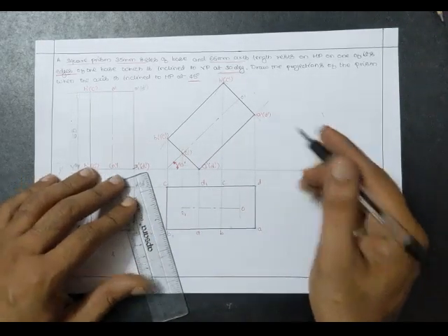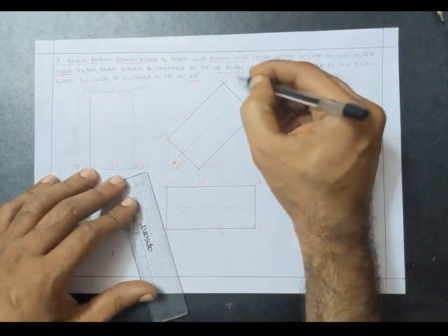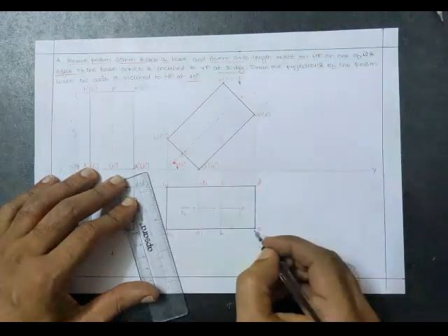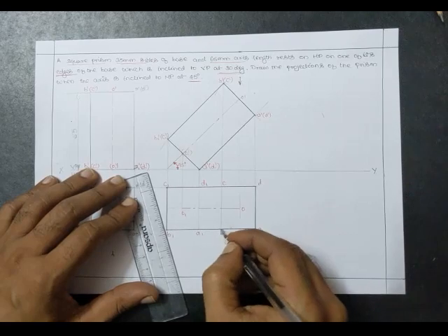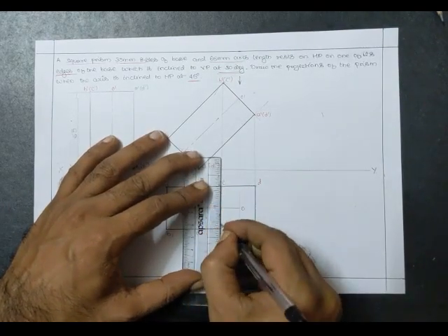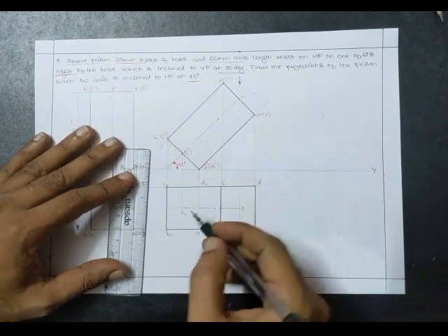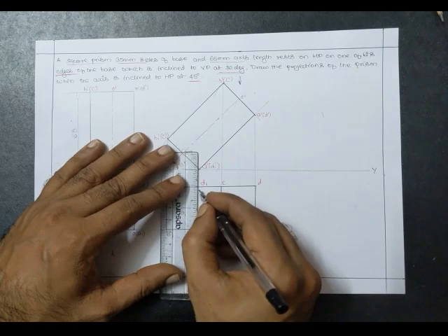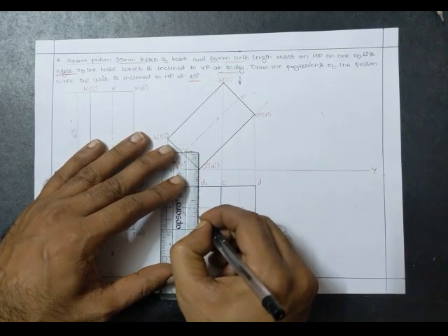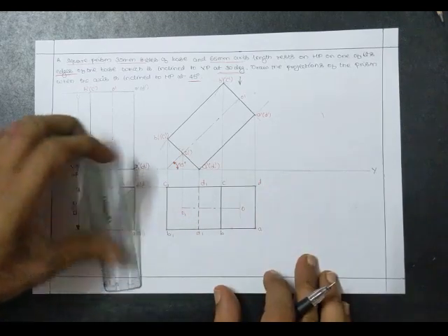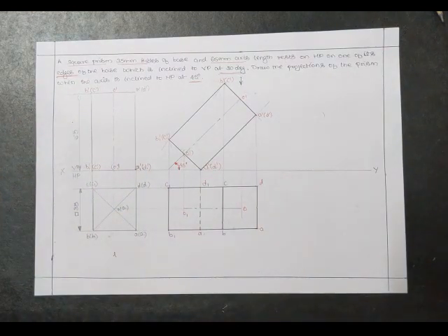When you see from the top, the top base is visible, that is A dash, B dash, C dash, D dash, that is A, B, C, D. A to B is already under a boundary. The only edge left out is B to C, so I am going to make that one darker. When one base is visible, obviously the other base is invisible, so I'll make the resting base edge dotted, and the rest I can't do because they are under a boundary. This completes the second position, top view.